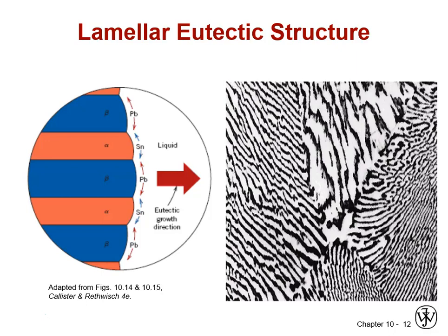So this happens very quickly, and it forms these spontaneous tight layered structures, and that interlayer spacing is dependent mainly on cooling rate. These can give you fabulous mechanical properties because dislocations will pile up at the boundaries between these phases very, very quickly. They're very hard, and they're basically a spontaneous form of grain refining that you didn't have to do a bunch of thermomechanical processing to get.